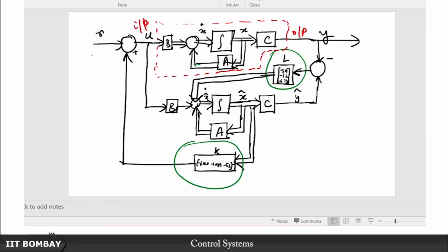Then we also talked about the complementary root locus, which is when the gain varies from 0 to minus infinity instead of plus infinity, and we saw how the rules of the usual root locus are tweaked, again depending on just an application of this angle criteria, right. So we delved pretty deep into that, and finally we concluded that discussion on root locus by seeing how you can design these well known controllers such as P, PI, PID, lag, lead, lag-lead, all these different types of compensators.